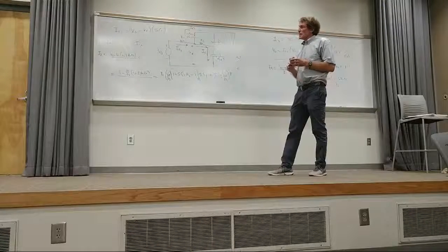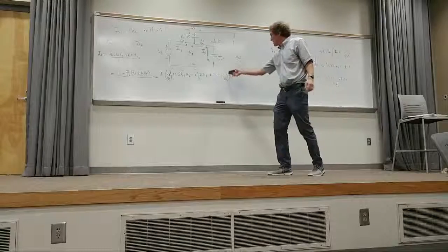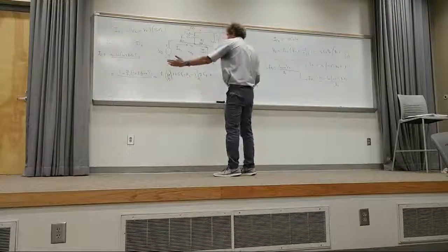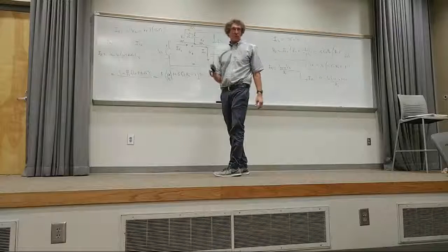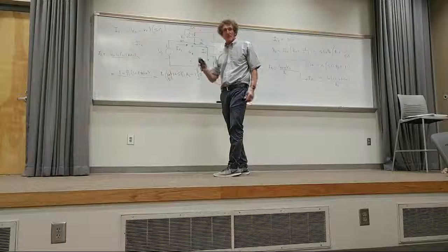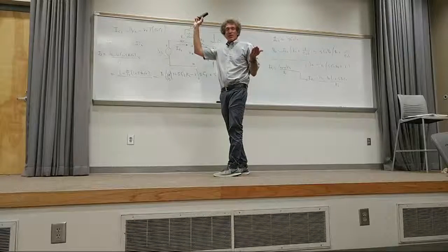And then, do y'all feel you can solve for V out over Vs yourself? And this one from here on? Here it is, V out over Vs, V out over Vs, V out over Vs. You would take all the V out over Vs terms to that side, everything that's constant or functions of R, C, or S to the other side, and just divide by the coefficient of V out over Vs. How many see that there? Can you do it? You're very quiet right now.